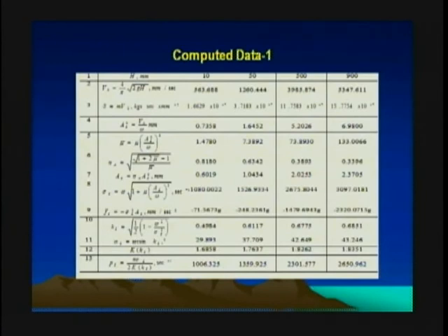For instance, the linear amplitude increases, of course, dramatically, but the nonlinear amplitude increases only a little bit, certainly by a factor of 4. Here you see the maximum acceleration. Certainly, yes, it's significantly higher, as it should be in highly nonlinear systems. It's 2,300, while with a small degree of nonlinearity, it's only 71. You remember we discussed a factor of 3, and that factor of 3 certainly manifests itself. Slightly nonlinear, almost linear, 71, and highly nonlinear, although a different approach was used here, 2,320.